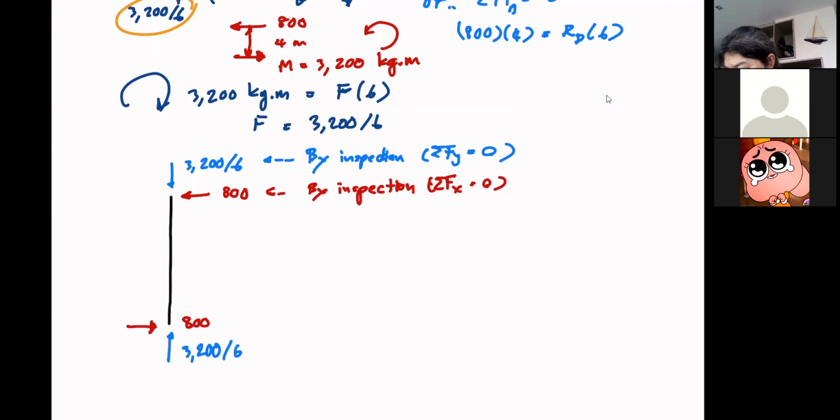Maybe, I kind of like to draw the support so that I know we are dealing with the hinge here. What are we missing here? The blue forces, the axial forces, they coincide, they act on the same line of force, so that's over and done with. But your 800s, they do not coincide. So without a moment, these 800 horizontal forces will cause your member to rotate.